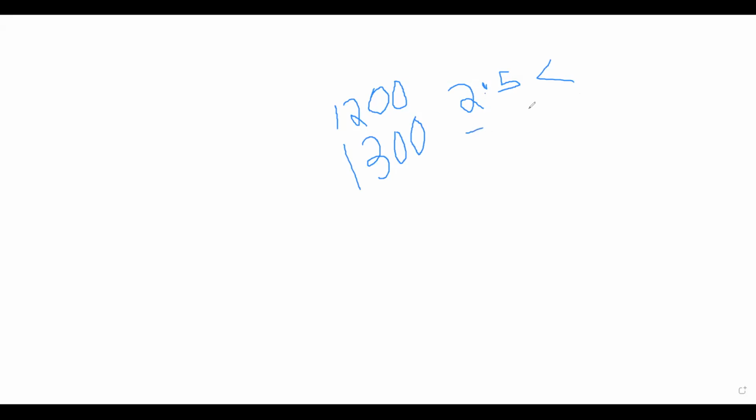Fine. So let's keep the limit as 2.5. Okay, and then let's proceed with the next step. Only 1 column is showing this result, right? Yes, sir. Okay, then leave it, no problem. If 1 column is showing that, we will increase the concrete area over that column, or we'll increase the reinforcement. We'll keep this reinforcement only in that.